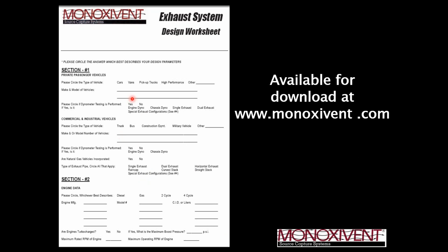So I would like every answer completely filled out. I never get that, right? More information, the better solution we can come up with, but I never get that. So at the very least, I need to know cubic inch of displacement or liter size of the engine. Horsepower of the engine doesn't give me what I need. Cubic inch of displacement or liter, I can convert them back or forth. And then maximum operating RPM of the engine.